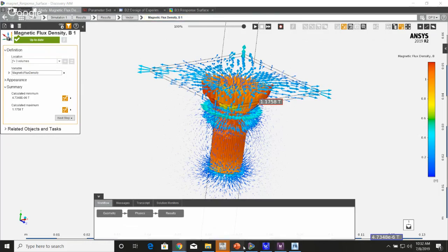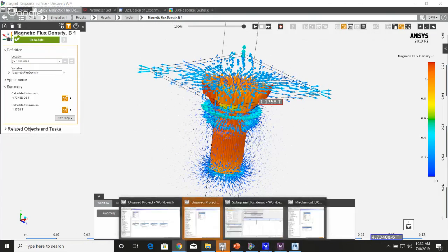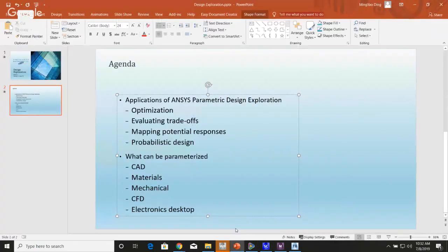Okay. So that's a nice feature that we've been working with for a while with a number of companies on the magnetic side. It's also applicable to a lot of different control system design as well as actuators. If you have an electrostatic actuator or a magnetic actuator, you can define the force-position plot for the entire domain and then use the simplified model to try to control your actual system.